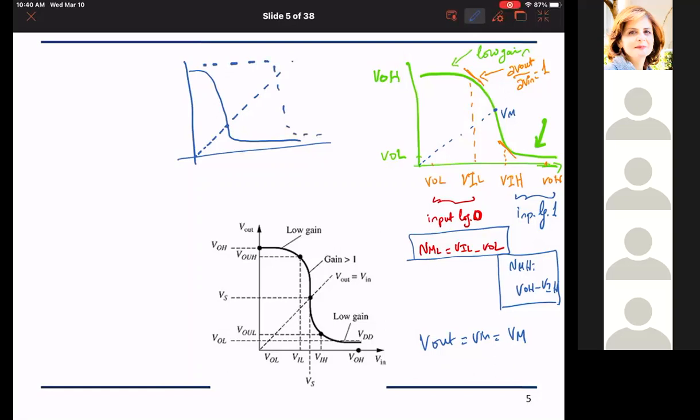So it tells me how balanced my circuit is and what it favors, and I prefer, of course, that my circuit be balanced and favor the high output as much as it favors the low output. We call it VS because it is the switching point between high and low, roughly the place where the circuit is going to start to go below the 45 degree line, meaning flip from high to low.